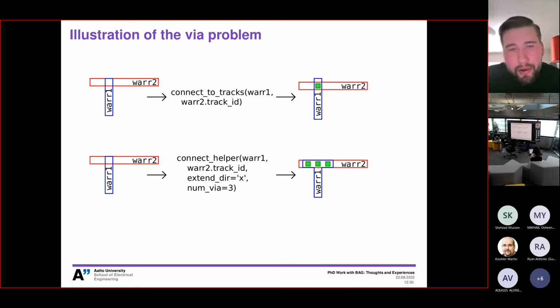Of course, the framework has convenient helpers for checking whether you can route to this coordinate using a certain track. But in order to minimize the interconnect resistance, you may have to resort to these hacks, and then you may create more problems than you want, and you have to ensure that you don't get shorts if that happens to be possible.